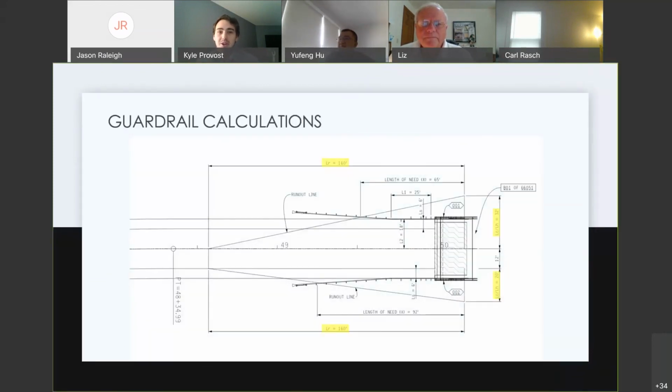When designing guardrail, the team used a geometric approach using MicroStation with the help of MDOT's worksheets. To avoid a large amount of guardrail throughout the project, the team designed all fill slopes at a 1-on-4 grade, which is the maximum value before guardrail is required. This meant that the design was only needed at the bridge approaches.